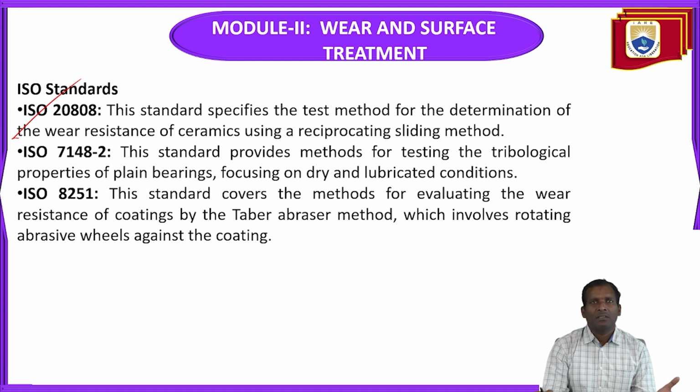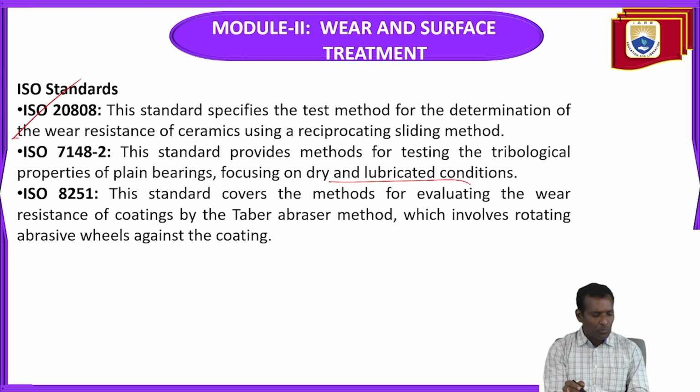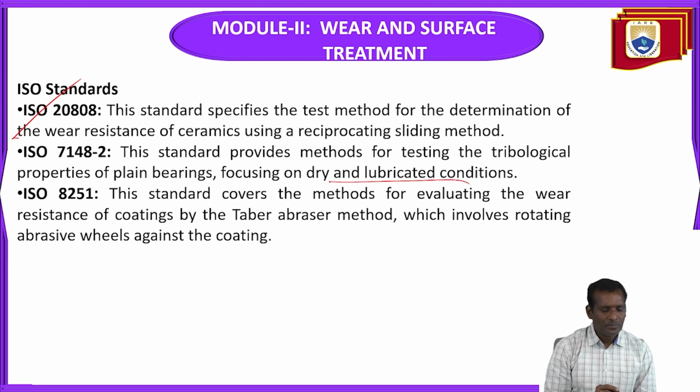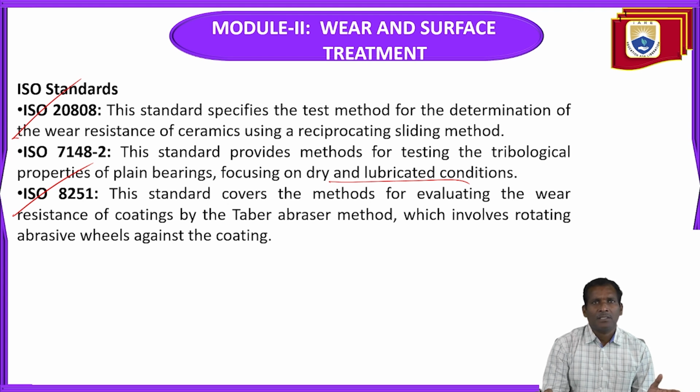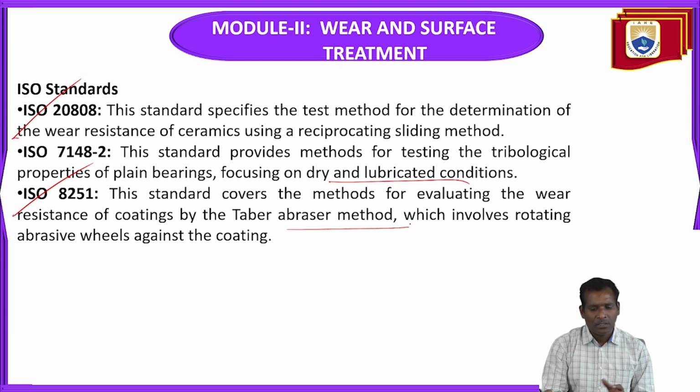Similarly, ISO 7148-2 provides a method for testing the tribological properties of plain bearings, focusing on dry and lubricated conditions. Similarly, ISO 8251 covers the method for evaluating the wear resistance of coatings by the taper abrasion method. It involves rotating an abrasive wheel against the coating.